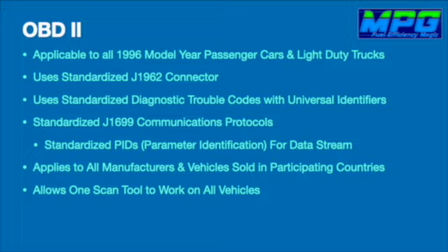OBD II standardized the connector. It's the J1962 connector, and usually it's found underneath the dash. That was even something in OBD I. Sometimes it was under the dash, sometimes it was under the hood, sometimes you had to lift the carpet to get to it. But the connector goes under the dash.